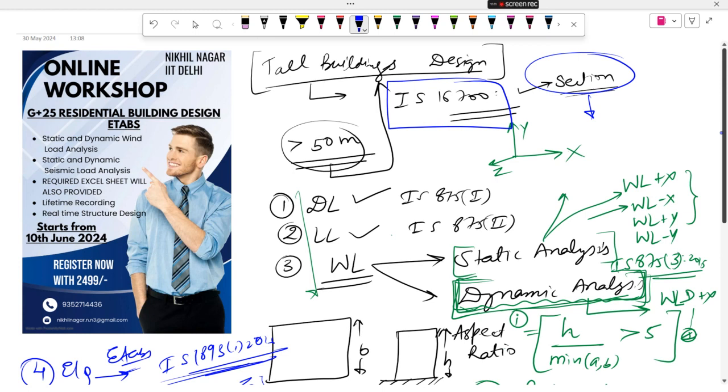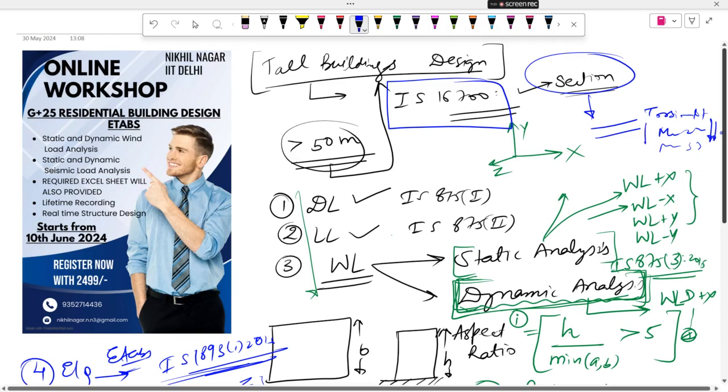It means we are just assuming that our beam, for torsional stiffness, moment 2 stiffness, moment 3 stiffness, has somewhat less strength. Okay, we are just assuming less stiffness so that our structure will be safe. Okay, it means we are on the safe side. So we are taking a higher factor of safety in our members. That's also in IS 16700.